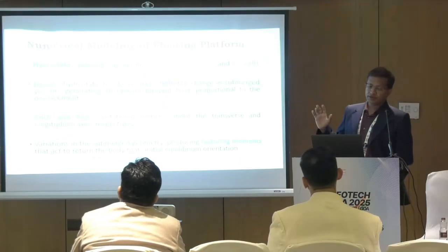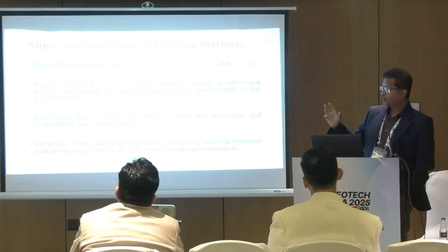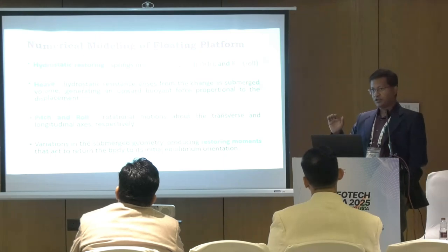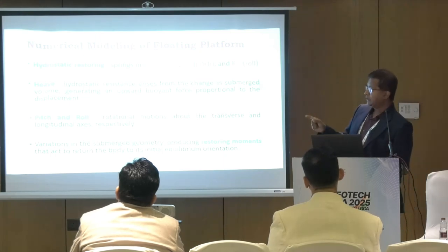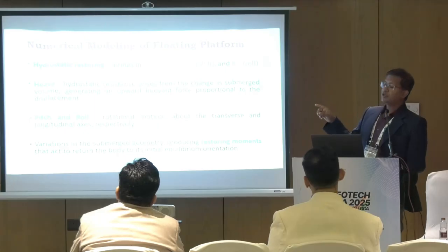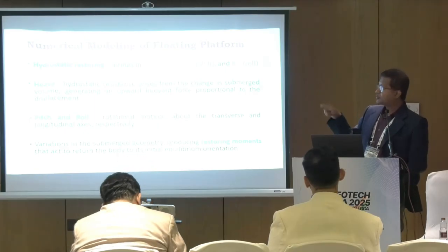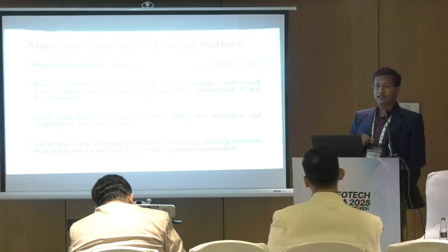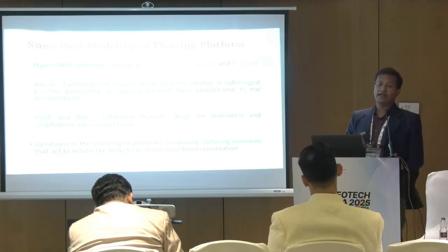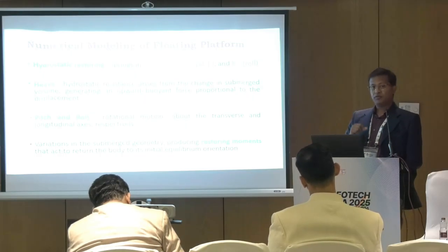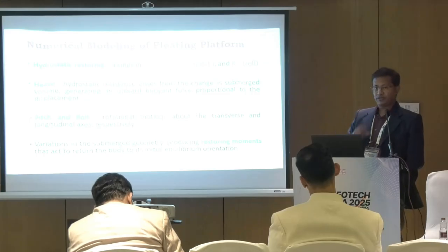The hydrostatic restoring for the different modes of vibration, the translational motion as well as the rotational vibration, is modeled by incorporating springs. Now how the spring stiffnesses are calculated is also challenging. It depends on the metacentric height, the density of the fluid, and the type of structure.